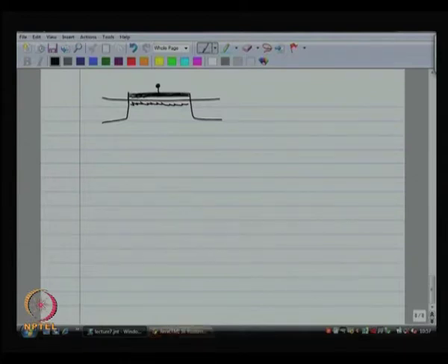This is actually something which is very popular, and the reason behind it is that the thickness of the gate oxide of a MOSFET is well controlled and very small. So, you get extremely high capacitance density and you get a much better controlled value of the capacitance than you would otherwise get if you take 2 metal layers.